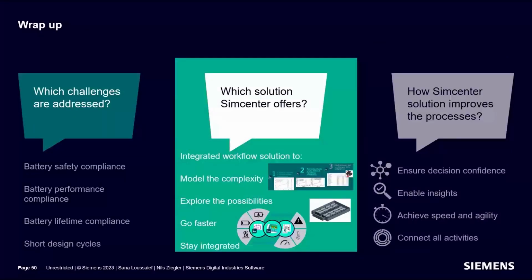Now, to sum up, the main challenges addressed in this webinar are the battery safety, performance, and lifetime compliance. And this is with short design cycles and development cost reduction. To address these challenges, SimCenter offers an integrated workflow solution to model the complexity, such as thermal runaway analysis, which is a multi-physics and highly dynamic phenomenon, or the battery pack model reduction, which is real-time capable while preserving high accuracy from 3D multi-physics simulation.